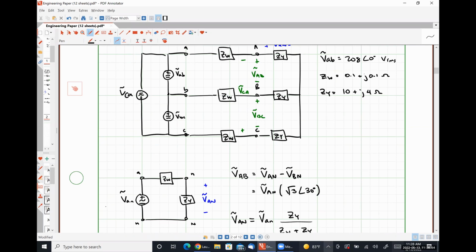So the single phase equivalent circuit method allowed us to use simple algebraic relationships, right? Whereas if we had not developed a means by which to transform from a delta connected source to a Y connected source, we would have had effectively a very large system to apply nodal analysis to, or a reasonably difficult system to apply mesh analysis to, right?